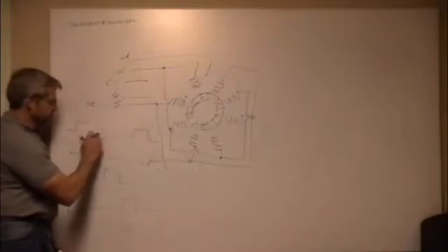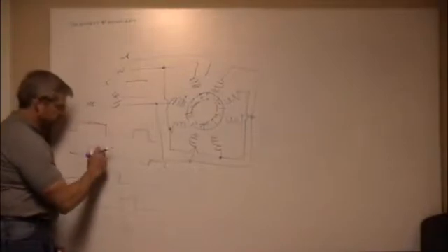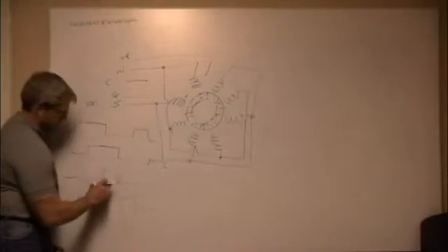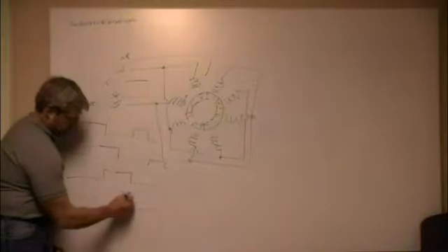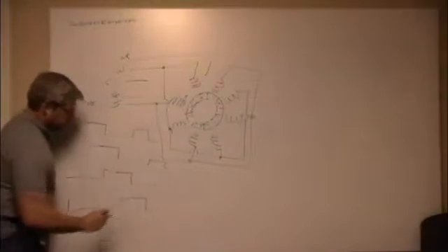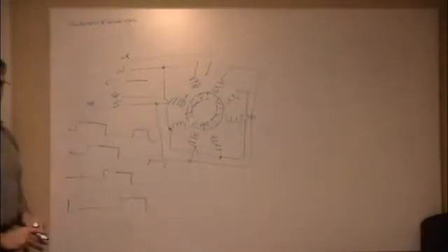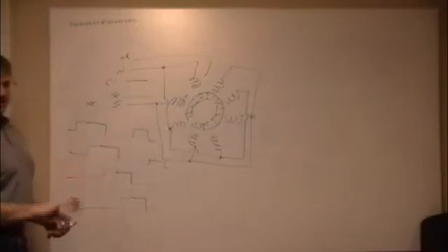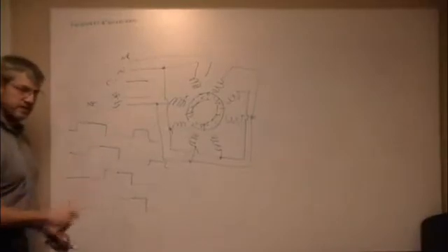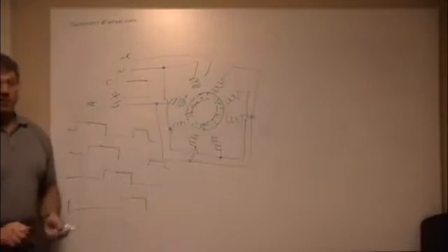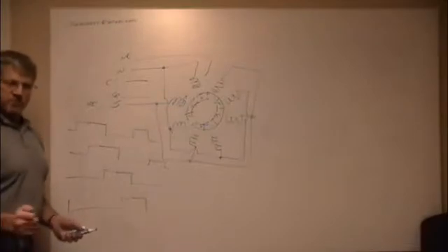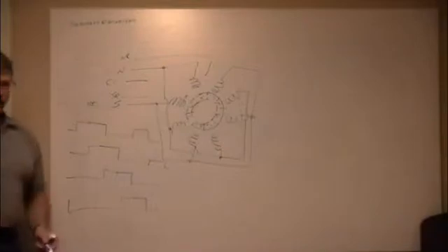Only one of them's active at a single time. What you'll normally see is called full stepping. So this turns on the north and the south at the same time, and bang, it steps. It's still only 1 step. It uses twice as much power, but it's got a lot more torque. It can move a bigger thing. It can hold against a stronger load.